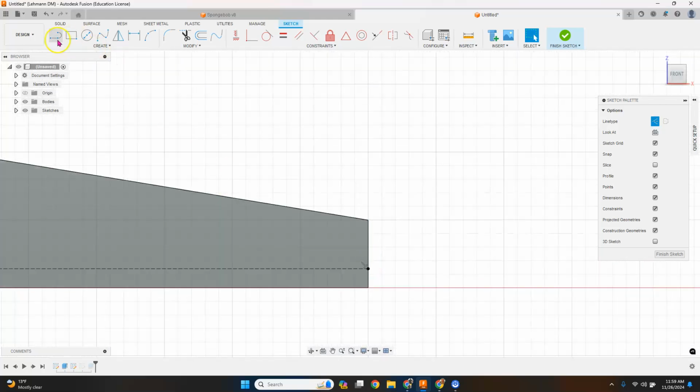and we're going to do the exact same thing with the line tool, where we select the edge. We slide down that edge, all right? And then from there, I want to type in, well, anything from 10 to 50. And I'm going to go on my end of my car, just 10, so it's really close to the end. And now I have that endpoint.